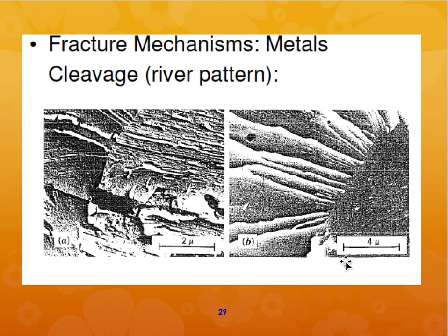So if it is a brittle material, you can clearly see that there is a small flat area in your sample that is close to the origination of the crack pattern. Okay, so that crack has come through here for a very short distance and then boom, it just radiated out like this. So you can see that the failure most likely started from near the flat fracture area.